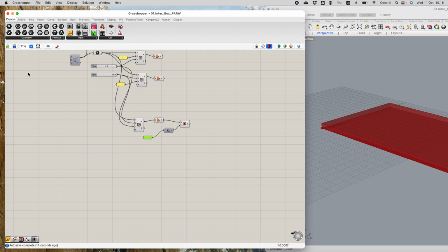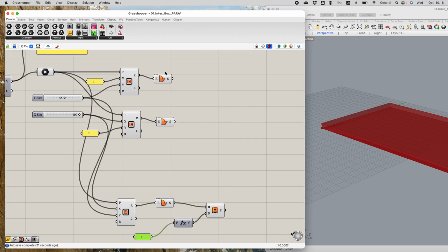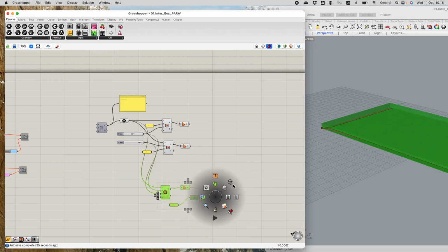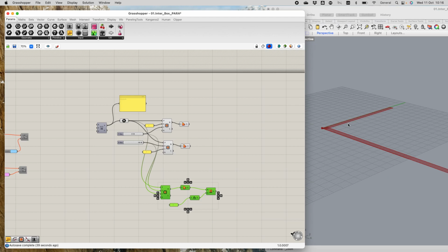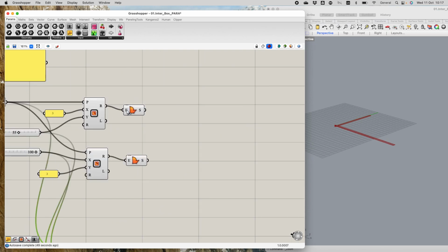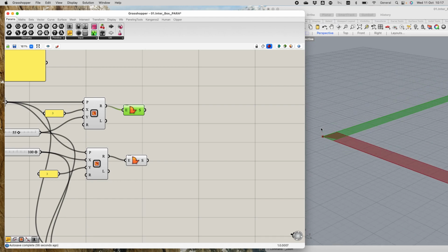Now, I want to move the side walls and extrude them. I was playing around with this yesterday, and I did the move first. So on these, let's hide these ones. Let's concentrate on the side walls. Before I extrude them, I want to move them into the right position. So let's look at the wall in the Y direction. And you remember, we want them overlapping for later doing the intersecting areas. That's quite important.